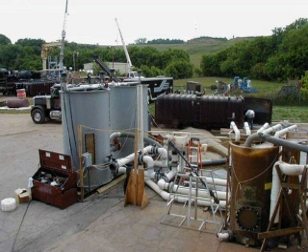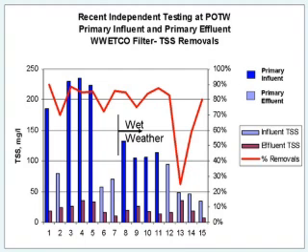It could actually then be used to, when the wet weather comes along, you stress your biological system, the clarifiers start to overflow solids. Compressed media filter, because it takes very high loading, so we've actually tested it up to about 1,600 milligrams per liter mixed liquor, and it removes these solids, 95% removal, and you can return those as return sludge back to the aeration system. And then also it could be used in treating the primary influent or primary effluent wastewaters if you have that kind of excess capacity or overflows from those parts of the system.